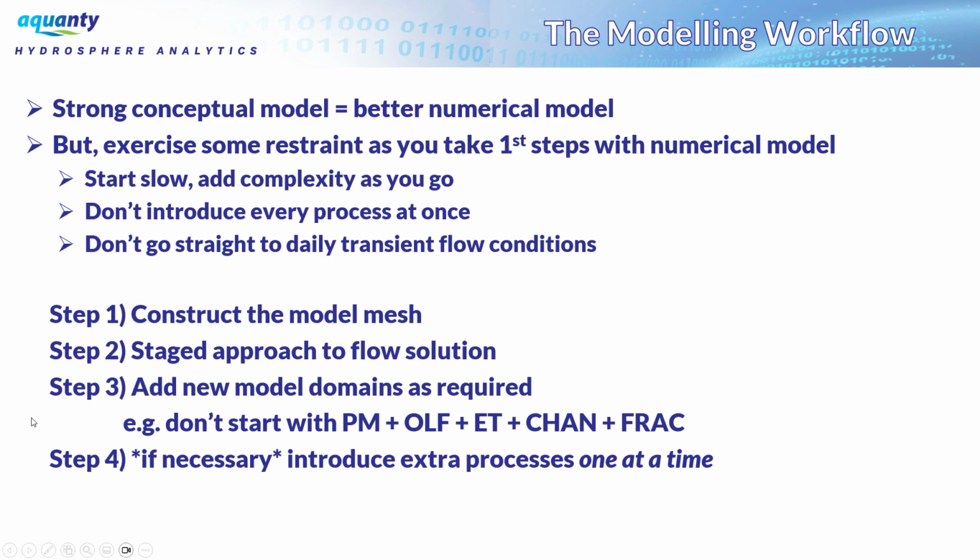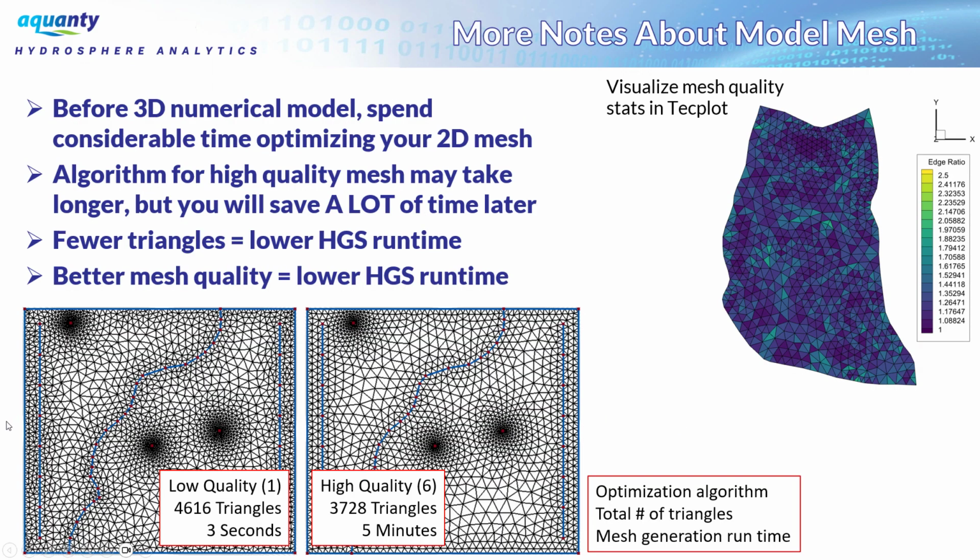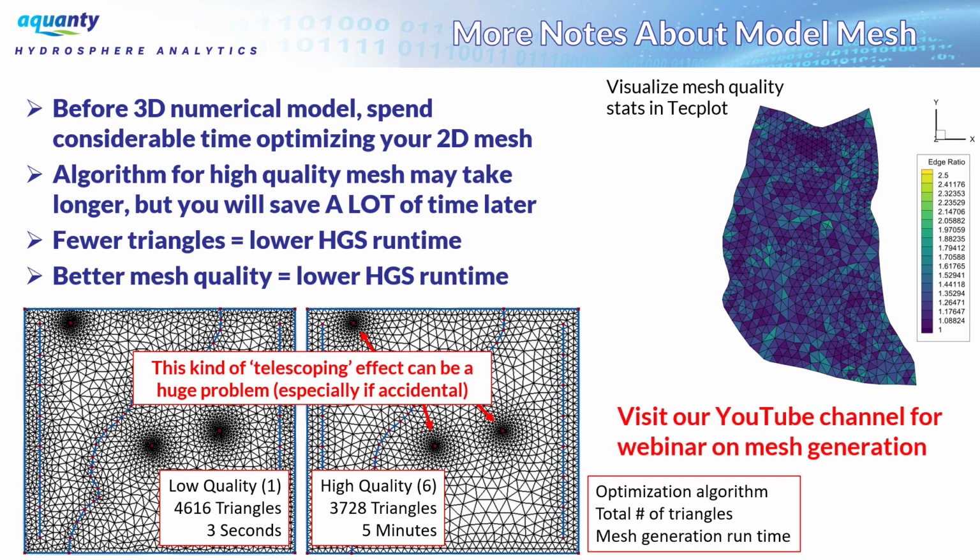So first of all, I'm not going to talk too much about building your model mesh. We actually have a webinar that we delivered last year. There's a recording on our YouTube channel all about that: how to build a highly optimized model mesh. But it is very, very much worth reiterating over and over that building a high quality model mesh should really be the foundation of every HydroGeoSphere model. Every minute that you put into building a higher quality mesh is likely going to save you many dozens of minutes further down the road as you go to run the model over and over.